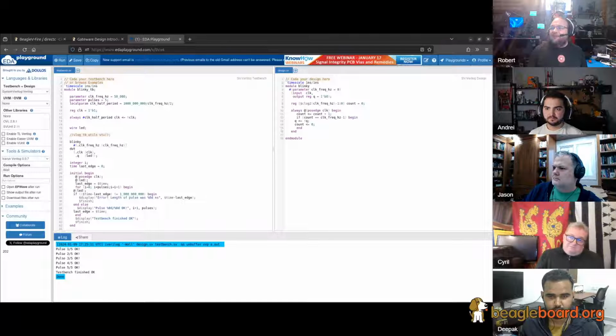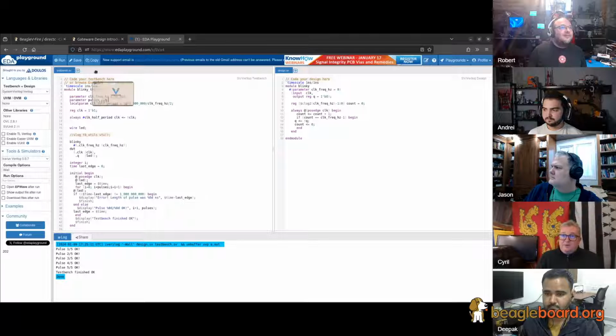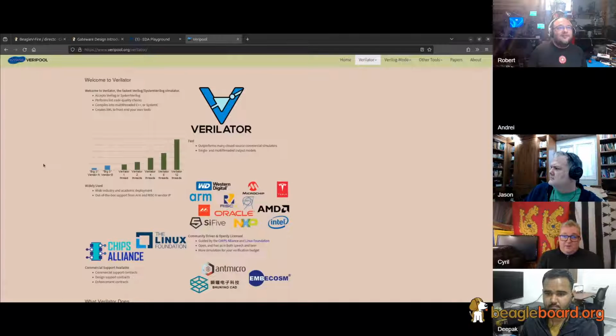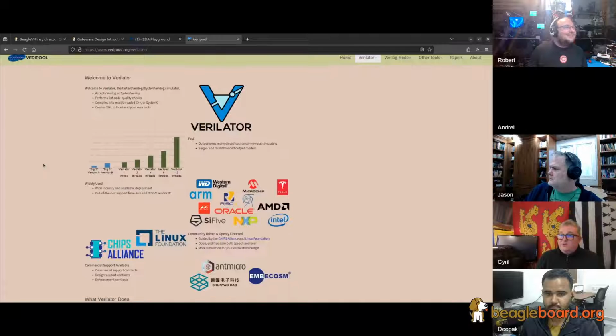And since we're trying to say that, hey, this is not an FPGA, we should have a big bunch of software people using these boards and have them in their comfort zone with C++. But there are many ways to do things. There's Verilator, but there's also something I find very interesting and valuable from the point of view of verification, which is formal methods. And for this, Yosys does have some features.